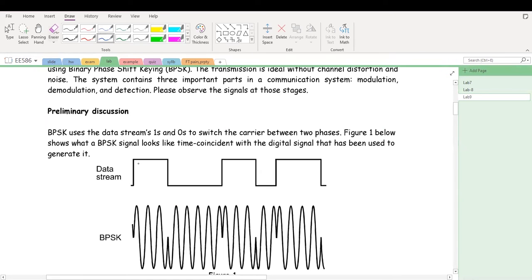So these are the digital bits 1, 1, 0, 0, 0, 1, 1, 0, 1, 1. And this step is pulse modulation. We use these pulses to represent 1 and these pulses to represent 0. So if we plot here, there should be a line here, so this should be the 0 line. The waveform has values, this may be some positive A, and this value is negative A.